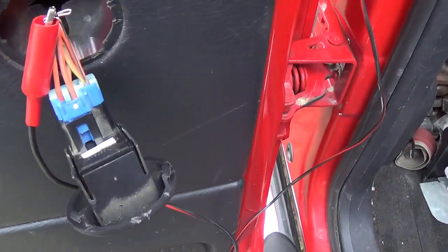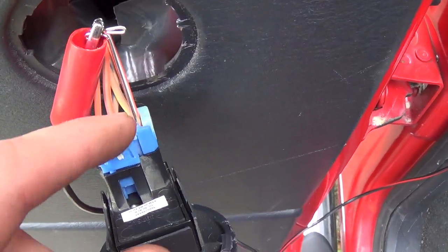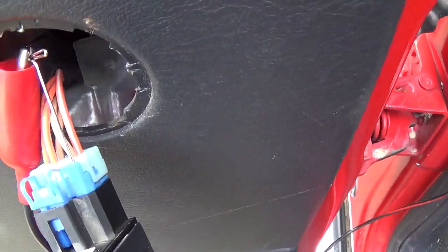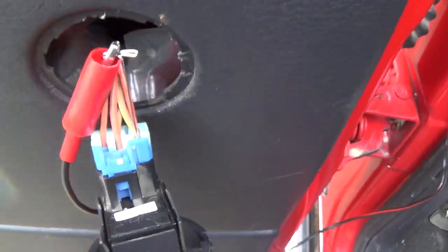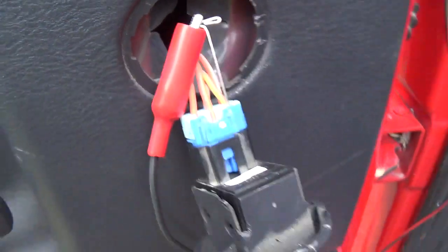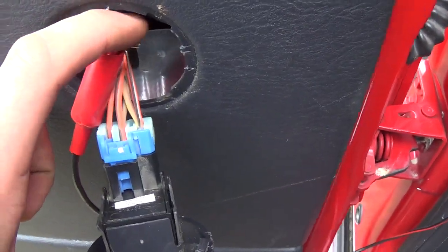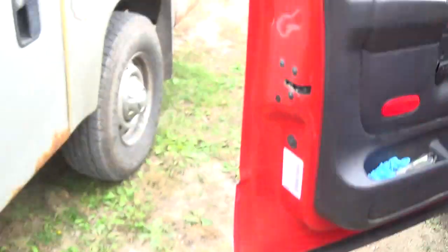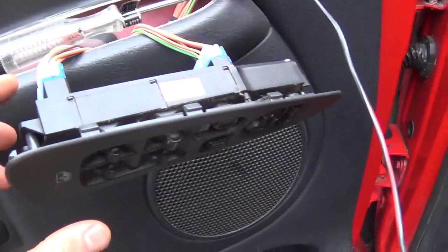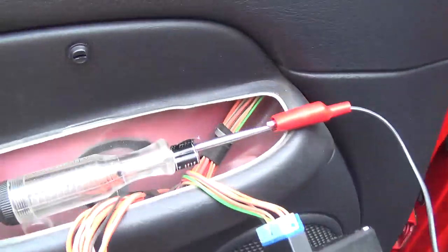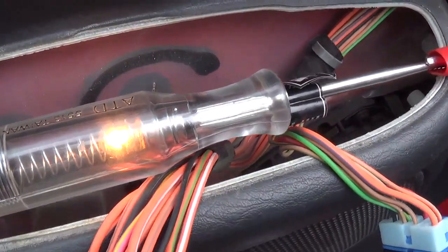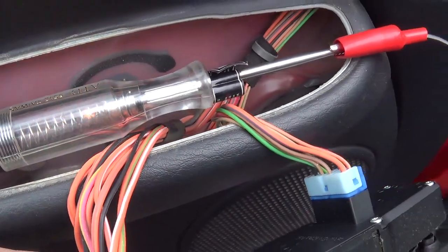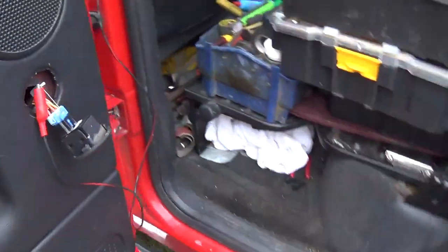Okay, I'm on the tan with a yellow wire, so there are 2 tan wires, and those obviously go to the motor itself, since the orange ones go to our master switch. So I'm on the tan and yellow, so let's flick the switch, see if anything happens to our test light. Okay, so I'm flicking that switch right there. So down, we get a nice bright test light. There's voltage in that wire. Now we have to check the other one.